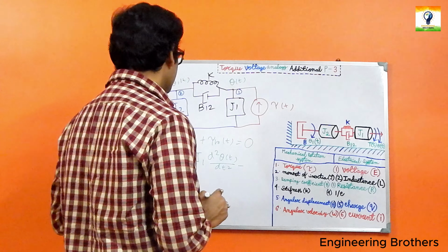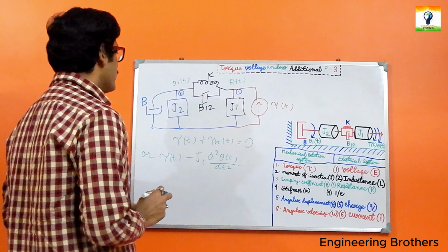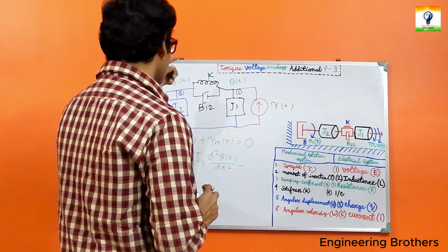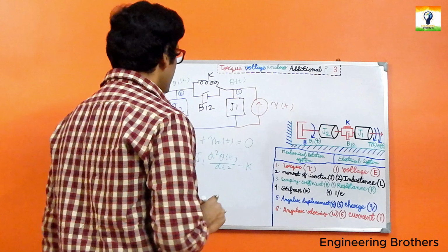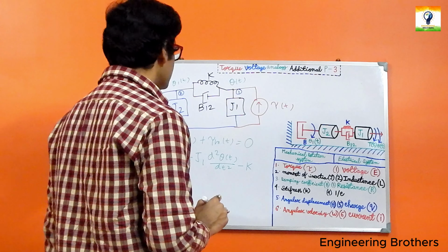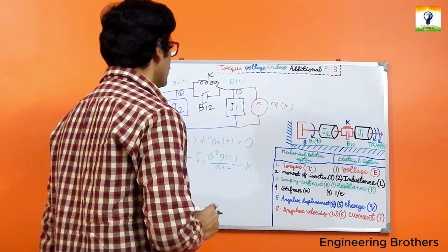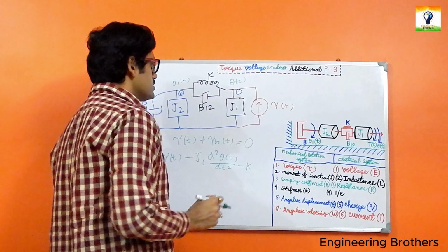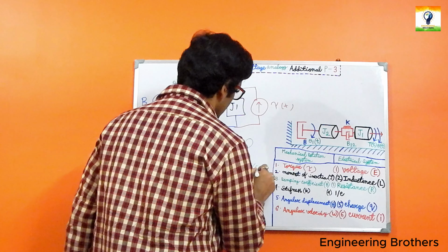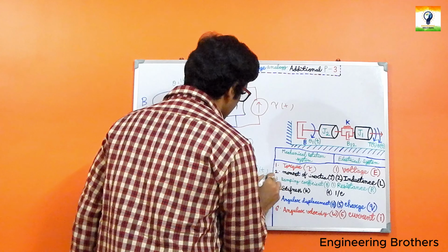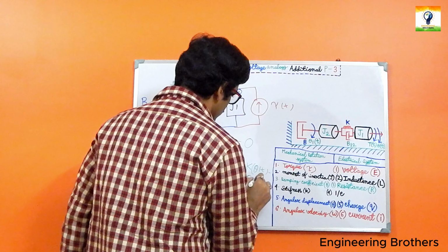So this is minus. Now go for the common part for this consideration. First I will take the spring element, multiplied with the resultant displacement, as we are taking 1 as our reference. So the resultant angular displacement will quite naturally be theta t minus theta 1t.